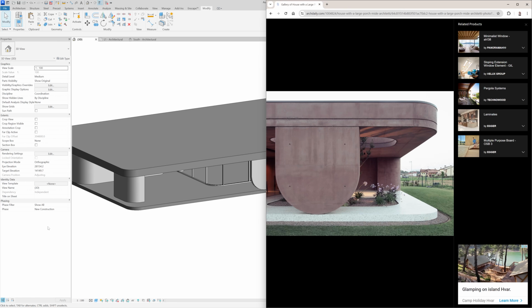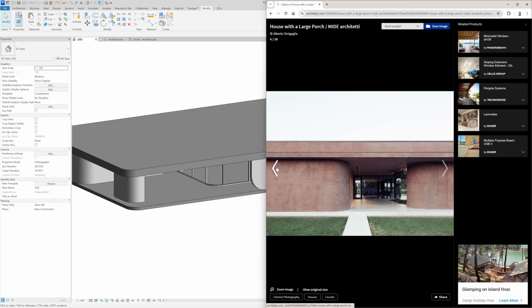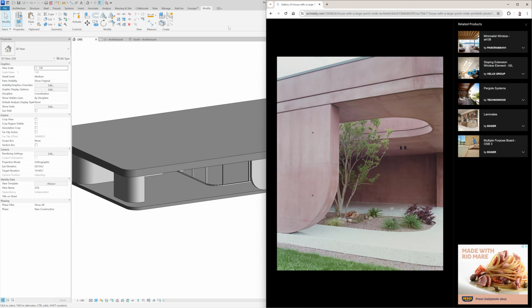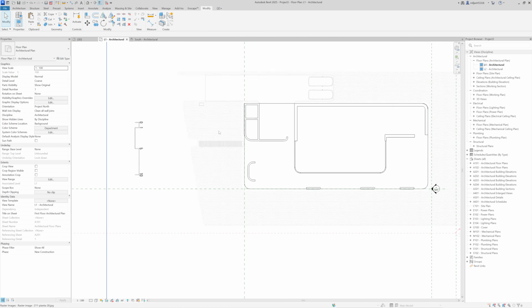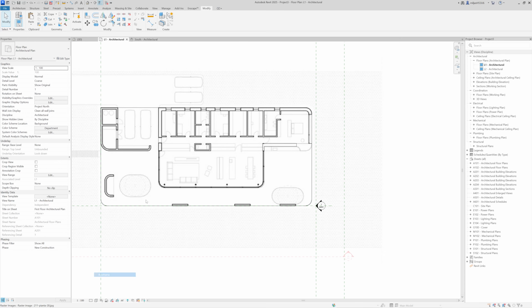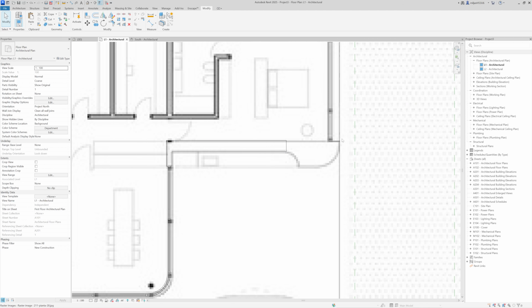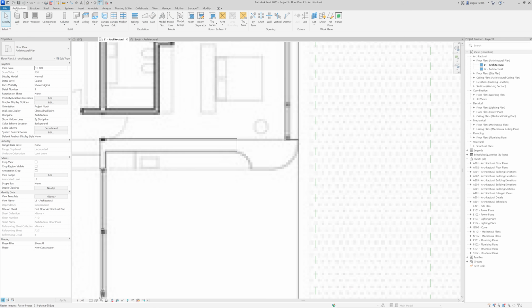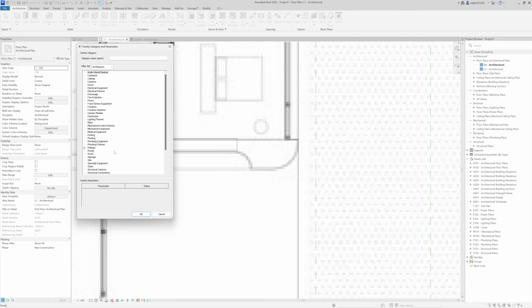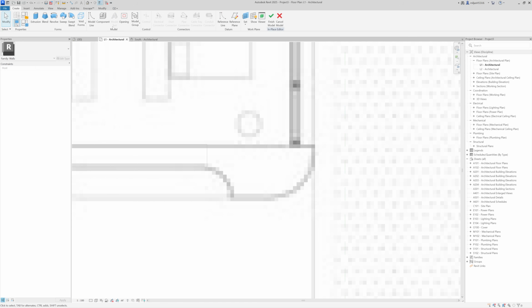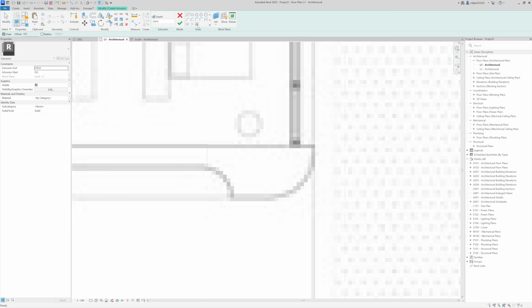As you could see, we have these openings here, on the floors as well as here. So I'm going to make it. And by the way, I forgot just one thing to do. Before I move to those openings, I need to fix this part here. And to be able to create it, I will go here to the architecture component and we'll take a wall as a category. So I'm going to make this part and we'll take extrusion tool.